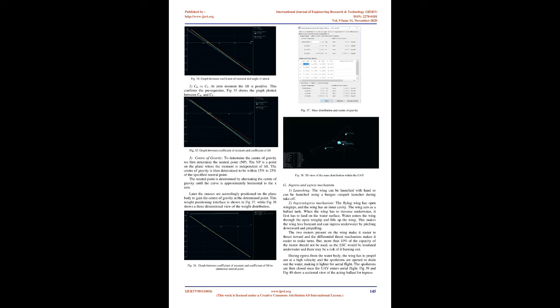The results were plotted for both above and underwater performance and can be observed in Fig. 22. The graph depicts the performance of the wing and compares above water performance to underwater performance. Most results coincide well with each other, except for lift-to-drag ratio and drag polar. This is expected as there is a change in density and kinematic viscosity of the two operating environments.